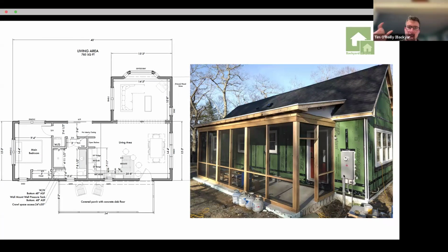That is R9. Inside of our walls is typically fiberglass. So you have a really well insulated wall with continuous insulation around the house. In the attic, if we're doing a flat ceiling or a cathedral ceiling, we're blowing in R60 of cellulose. And then it's a little bit hard to see here, but our foundation material is an insulated concrete form. So we have the structural concrete and rebar, but on both sides, we have about 2 inches of insulation. So it's an R22 foundation. So insulated foundation, insulated walls, insulated attic.